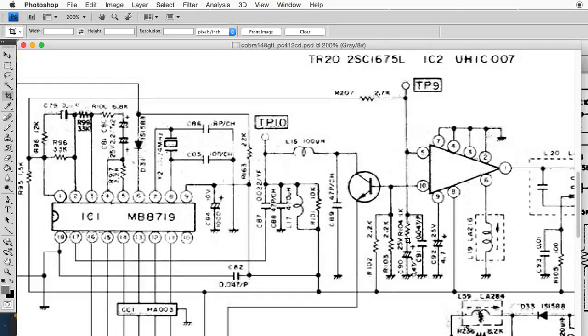this aspect of the filter system, which is important, definitely true, helps to improve the understanding of how it works. It isn't truly a voltage that comes out, it's pulses, and if you measure the voltage, you will see an average, but your multimeter, if you're not using an oscilloscope, won't show that it's pulses. It will show an average, and it's not necessarily accurate. At this point it will be fairly accurate because it's been smoothed, but back here it won't be.